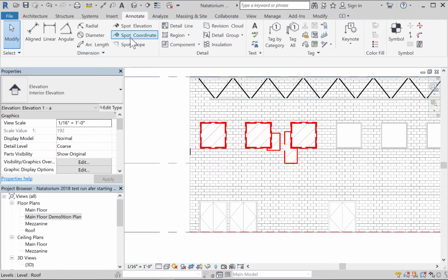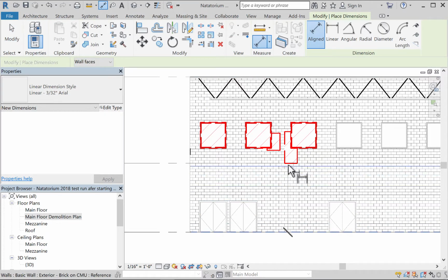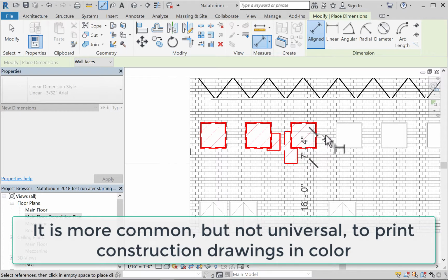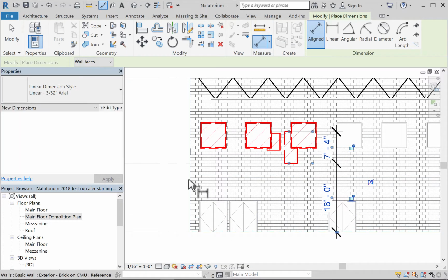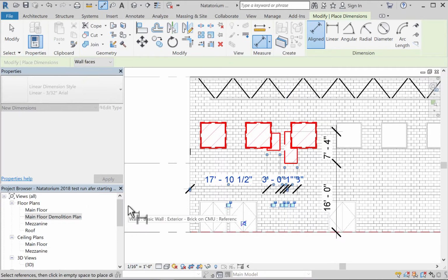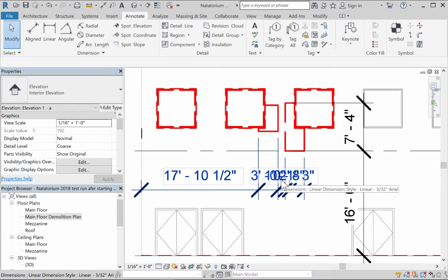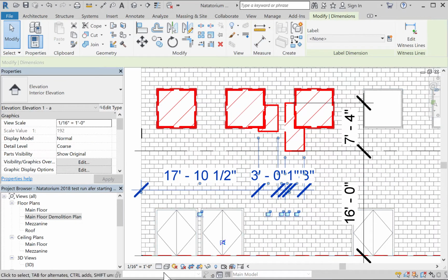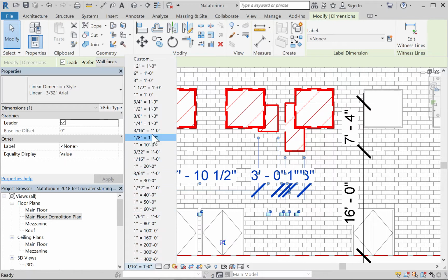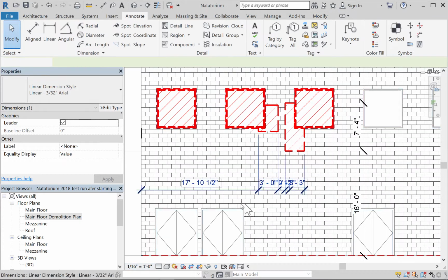All right. Anyway, and the other thing is that, like I mentioned, you have to put in a dimension. It's very important that you show both the height off of the floor, okay, and the location of these little devils off the side wall, okay? And as you may or may not remember, Revit can get pretty messy in these elevations. Oh, except these are 1/16 of an inch. That's pretty small. Let's go with 1/8 of an inch.